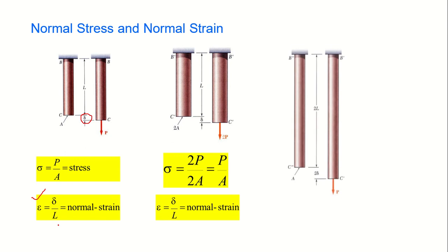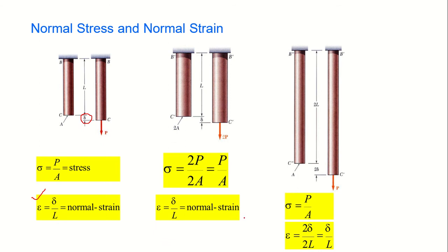Okay, again one more exercise. The length is doubled, deformation is doubled. At that time you will get the same stress value, then the same strain value. Okay guys, with this you will come to know that stress is not dependent on length. Okay, so here you will come to know that stress and strain are internal effects.